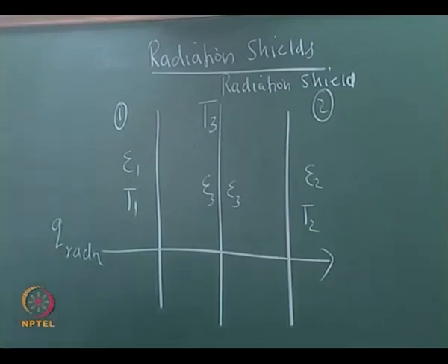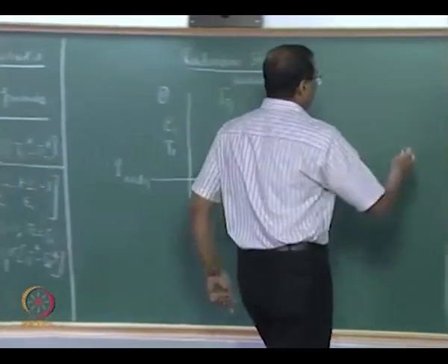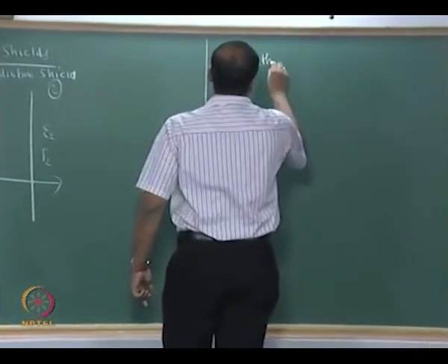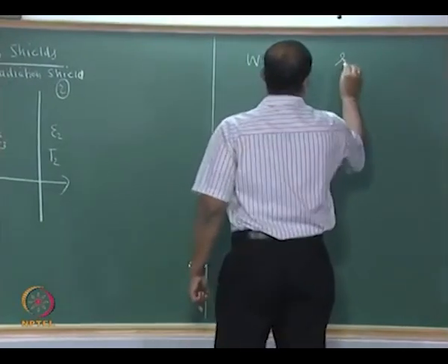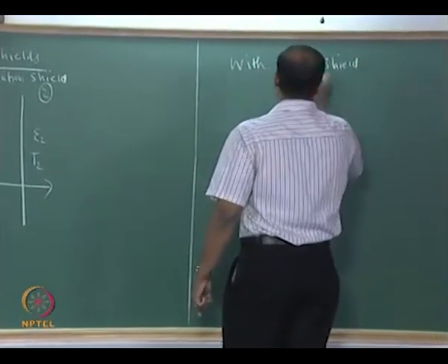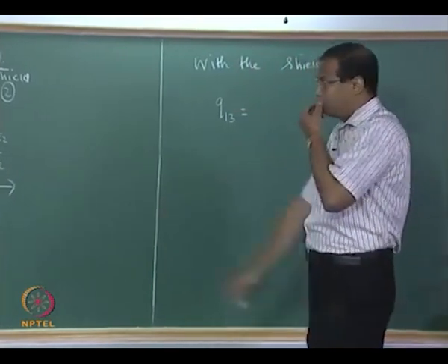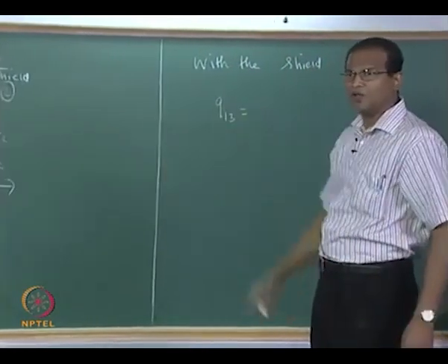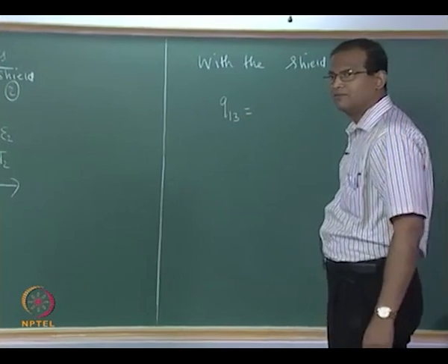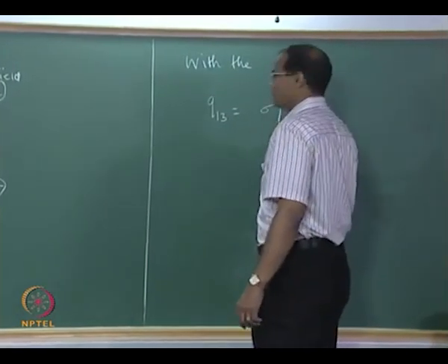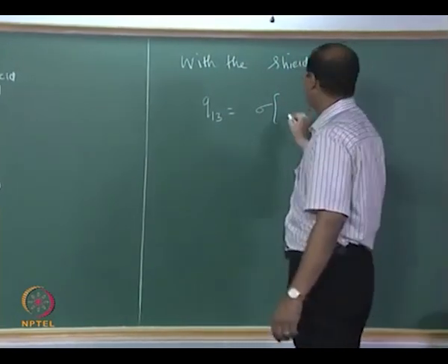So is the configuration clear? Now the challenge is to come up with a mathematical expression for Q with the shield. Okay. Q13 can be written, from the parallel plate formula, as sigma T1 power 4...